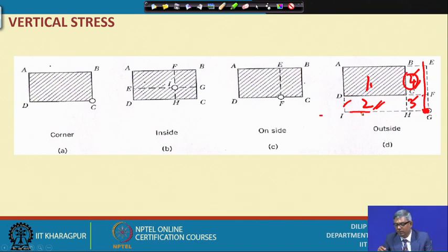I will apply the corner formula for this with negative loading, so it will be subtracted, and again apply the corner formula with negative loading, and again it will be subtracted. By doing this, you can see that I am subtracting this area twice, which is reducing too much. So finally, I can again apply the corner formula for this and add.